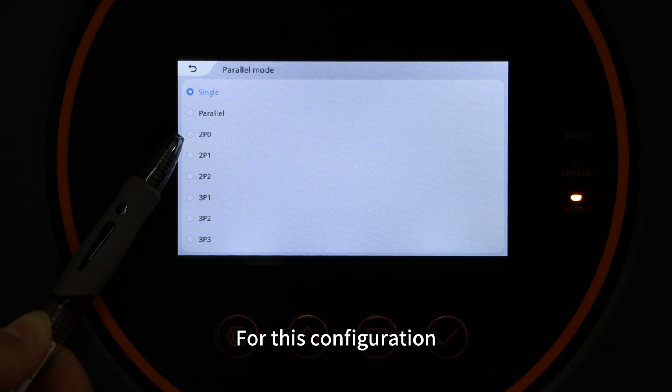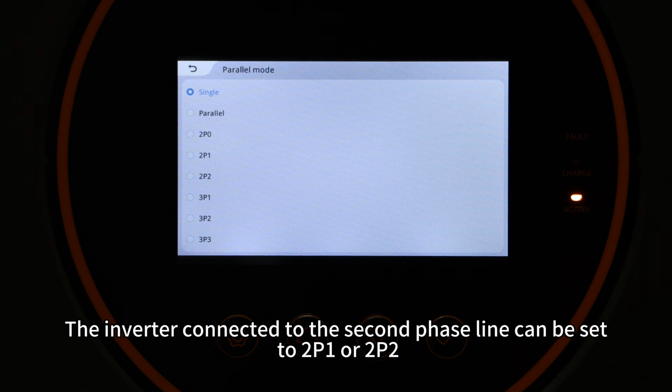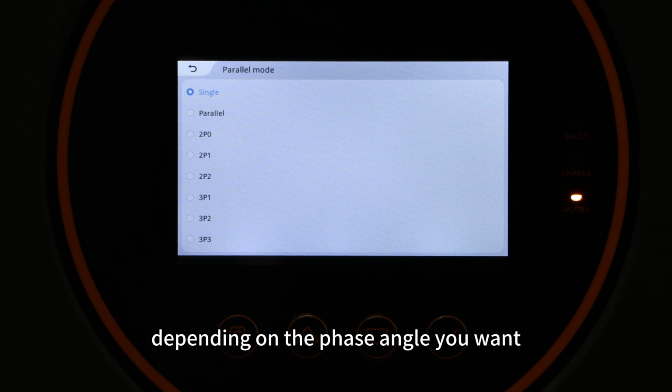For this configuration, the inverter connected to the first phase line should be set to 2P0. The inverter connected to the second phase line can be set to 2P1 or 2P2, depending on the phase angle you want.